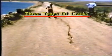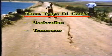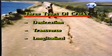Cracking is another deficiency to be alert for, especially cracks that are new or enlarging. 3 types of cracks are found at embankment dams: desiccation, transverse, and longitudinal. These different crack types all have meaning with regard to the performance of the structure. Therefore, it's important to be able to describe any crack you observe by type if you can.